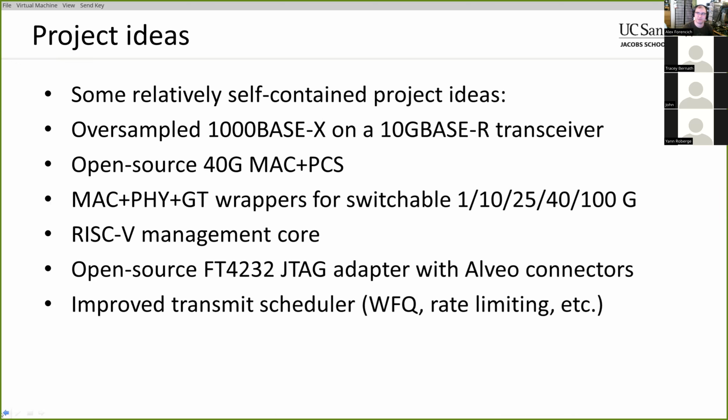It's not something I've looked into recently, but there's a lot of different RISC-V cores out there, and I guess we don't necessarily want to pick the absolute smallest one possible, although we certainly could. There might be one that's slightly larger but also provides some useful features, like debug interfaces. I know the VexRiscv in particular does, but there might be a few others as well, where you can basically enable JTAG on that core, and then you can bring that out to user space somehow.